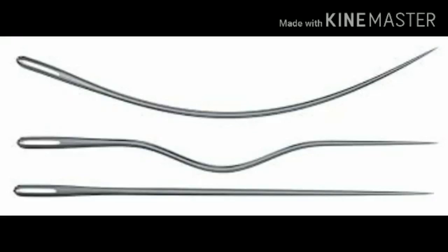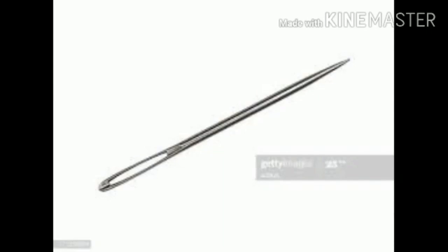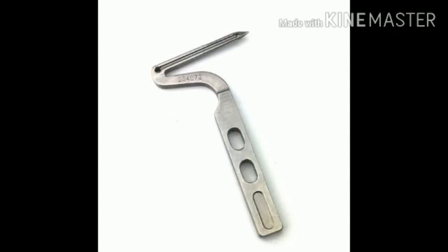Causes of failure. Number 1. Using the wrong size needle. Number 2. A bent needle, which results in low quality of products and ultimately needle breakage. Number 3. Needle may be in loosely. Top tension is too tight or thread is wrapped around something. There are three other types of failures too, which include looper damages, upper thread breakage, and lower thread breakage.